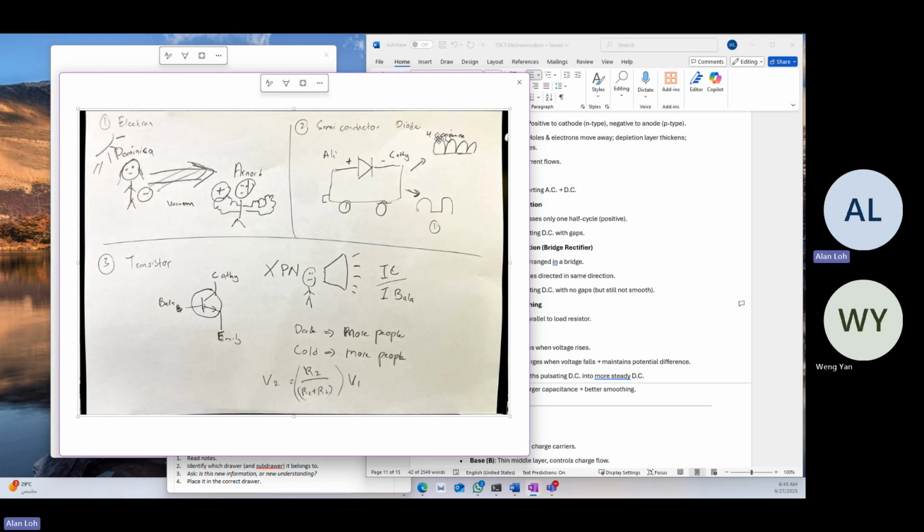You are being charged, then the charging is slower than the previous 1 second if it is coming over here. And then you go up again, then you go down again. Ideally, if it is a straight line, that will be the best. So how do we do that? We are using the capacitor. The capacitor discharges, so it will not go down to almost zero. It will be reduced, but not as bad as a drop here. Then it will form almost like a straight line. So that is the function of the capacitor.